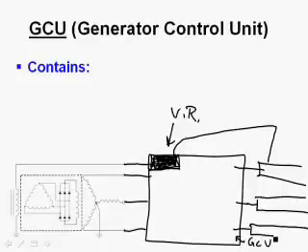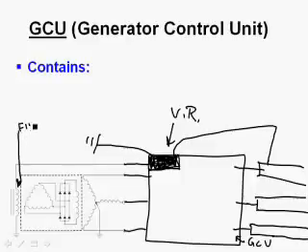We're going to have 3 bus bars so that each of the three phases are kept separately. Voltage regulator is going to be connected to at least one of them to measure it, and of course it's got to be connected to ground so it can measure that voltage, and then it can decide how much power goes through that field.